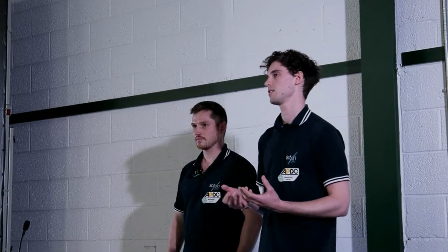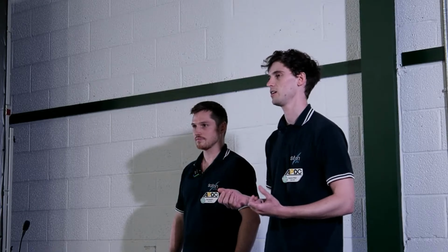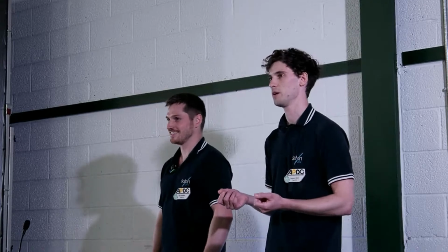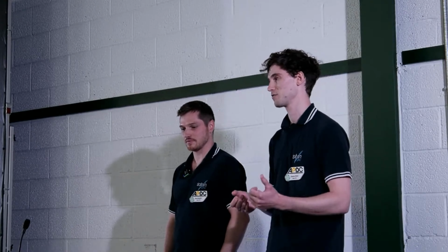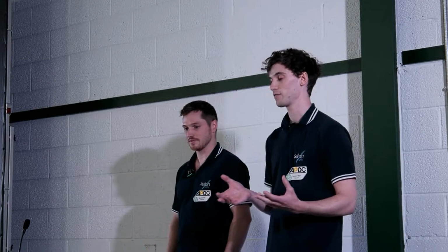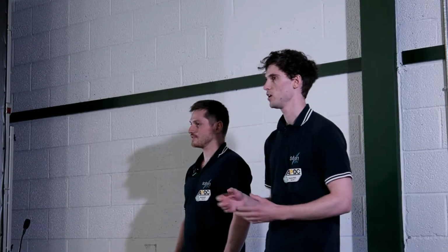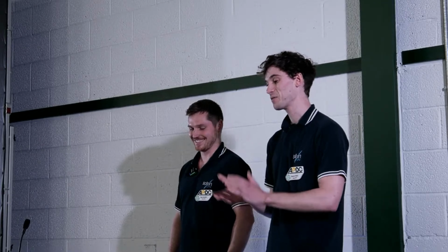We had one where a disarm command was set to the throttle channel. It was only in a high power state that it would disarm the aircraft. It was only because we were taking off from long grass that we could find that out. And we didn't know why for a little while, and then we debugged and found the reason why. So it's not always as simple as checking that they've got the arming checks on, which, believe me, every student turns off.